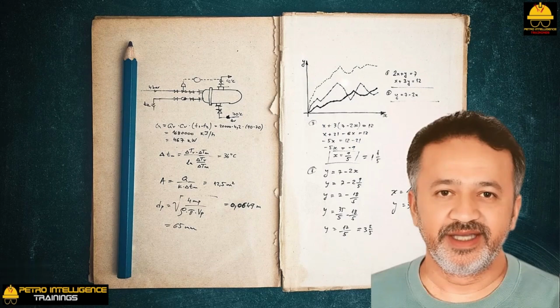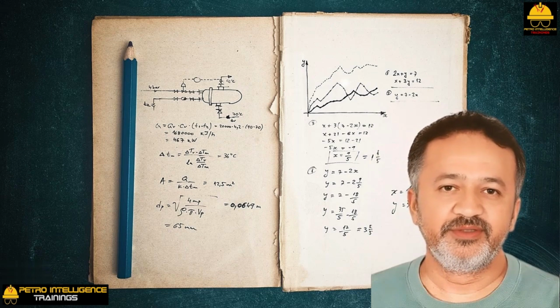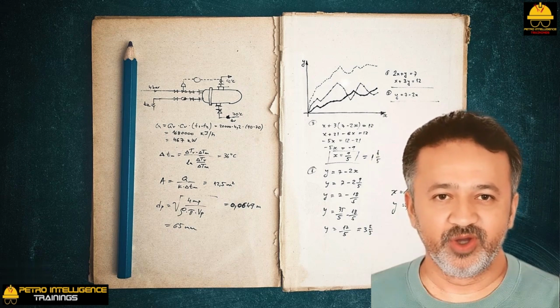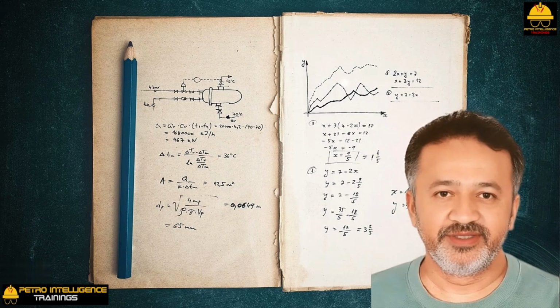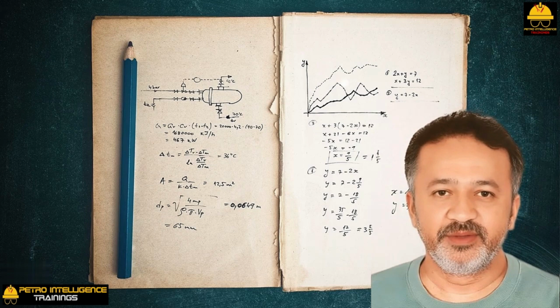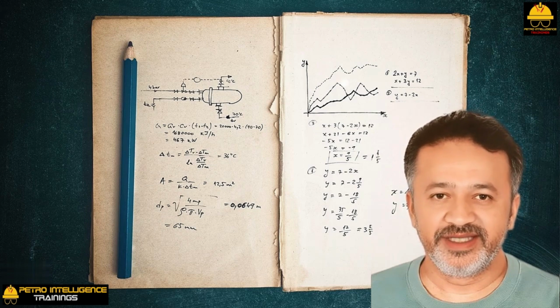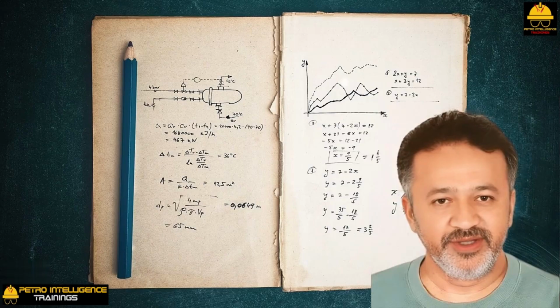How to convert heat into motion? I have 2 ways of expanding steam. The bad way and the good way. In both ways, I am not changing the energy content of the steam. I am not extracting any work from the steam, there is no friction, and no heat is added or lost. This is called an adiabatic expansion.